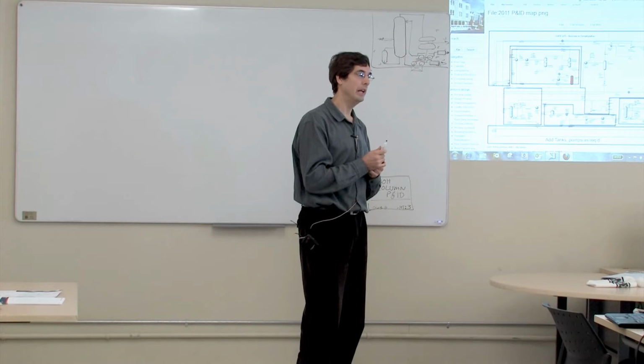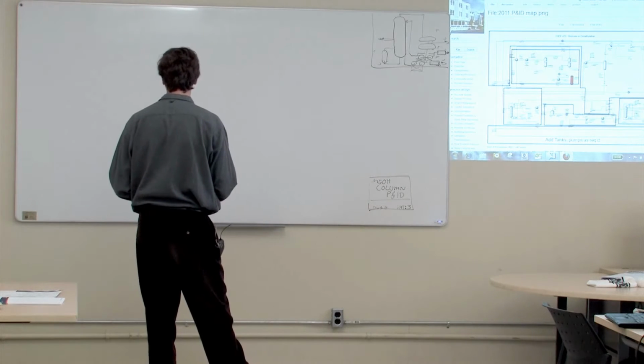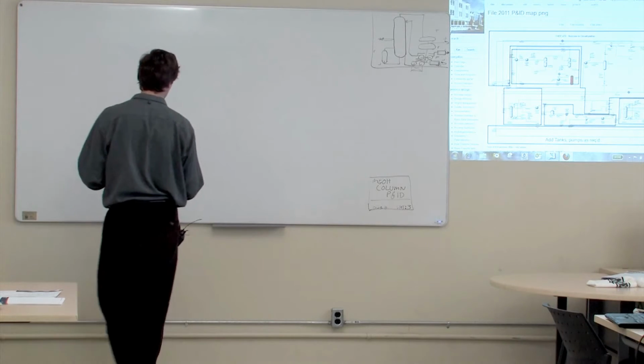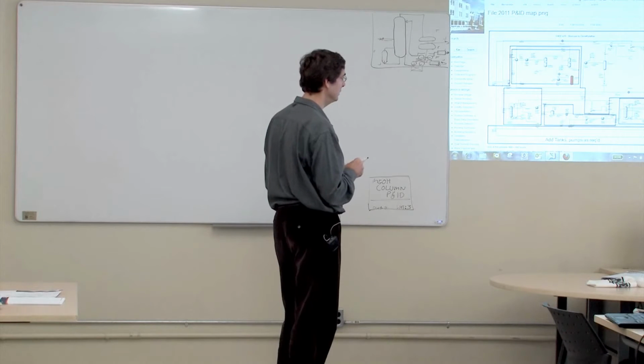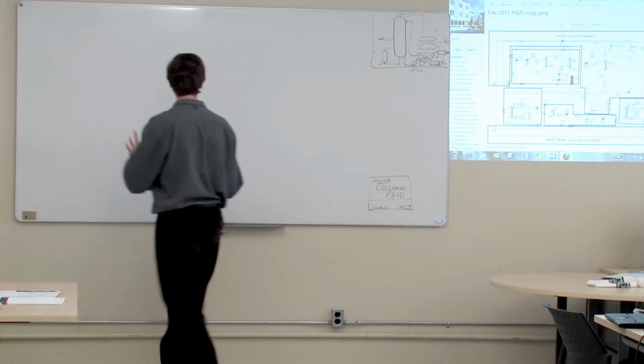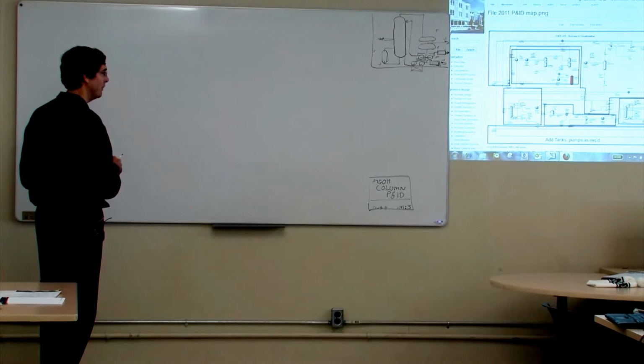If you wanted to increase the capacity, you could run bigger flows. Okay. I would have gravitated towards a thermosiphon first try. But the P&ID will look a little bit different for a thermosiphon versus a kettle reboiler, but it's not a big deal.